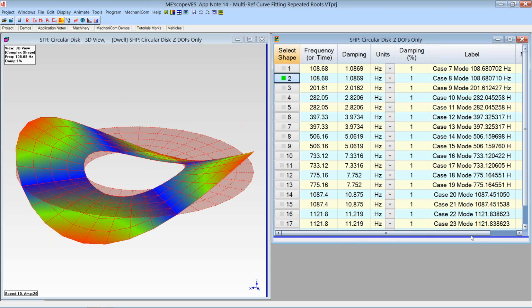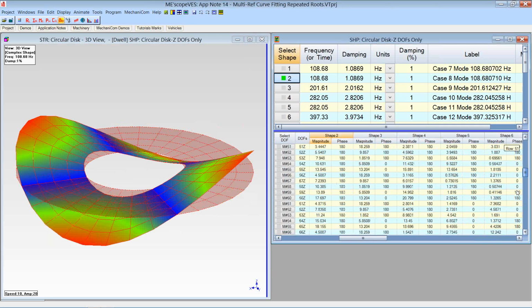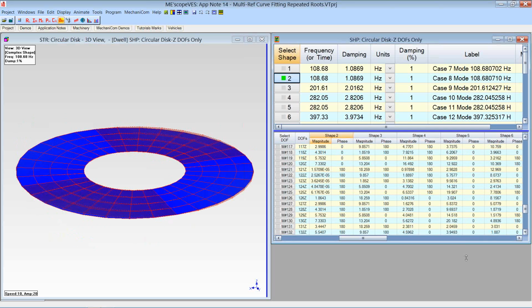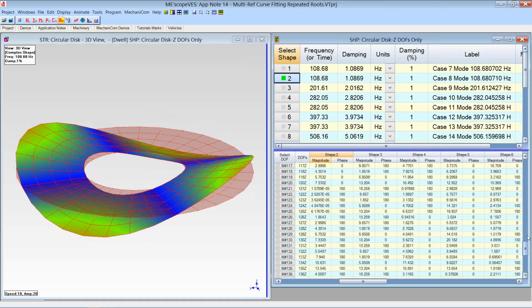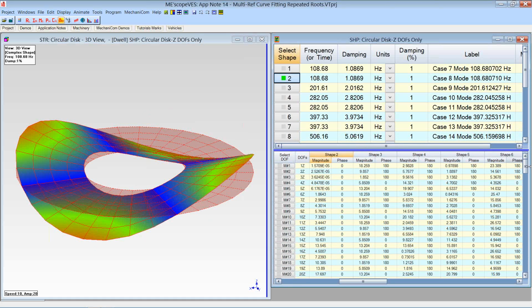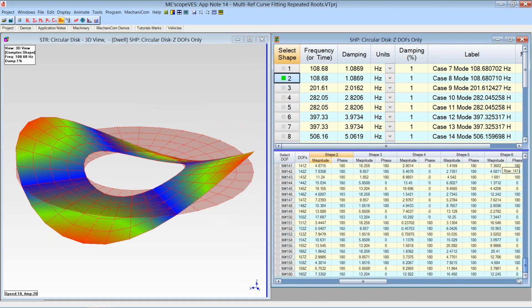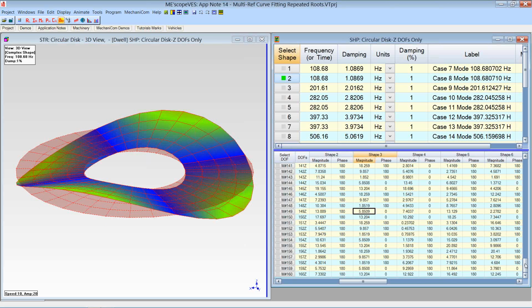You can see DOFs, when they come out of the FEA solver, there is no reference. The reference is only used when we curve fit FRFs. And we know that an FRF has 2 DOFs. Out of an FEA solver, we only have a single DOF. So you can see the mode shapes here have 160 degrees of freedom at 160 points in the Z direction. That's what we're looking at down here. Scroll that down a little bit.